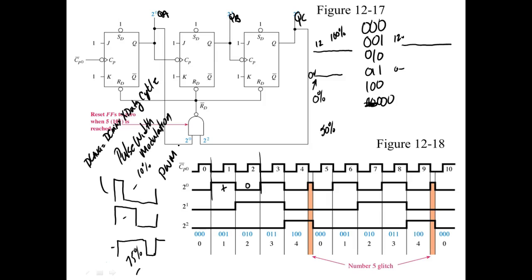We used to actually give it a different DC level, using these big things called SCRs and transistors and stuff like that. But the problem is that digital consumes less power than analog because it's either fully on or fully off. So if it's fully on, my control device is not dropping any voltage. If it's fully off, it's conducting no current.